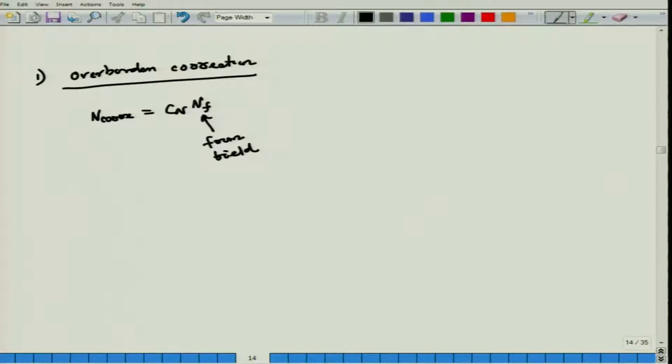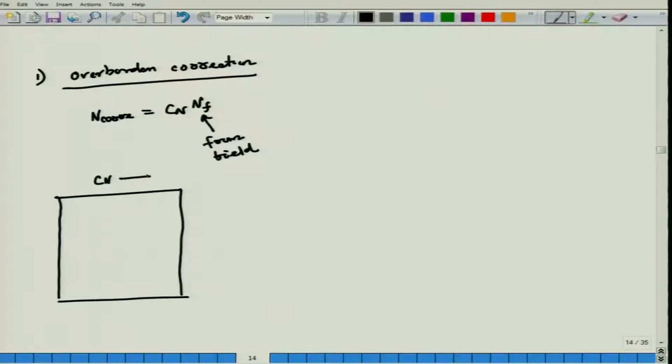As per your Bureau of Indian Standards, they have given a chart, you can download it, particularly for Cn corrections. Here Cn is varying from 0.4 to 2.0, and P, the effective overburden pressure in kilonewton per meter square, varies from 0 to 500. The correction is coming in this range.